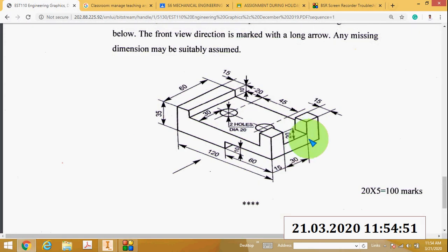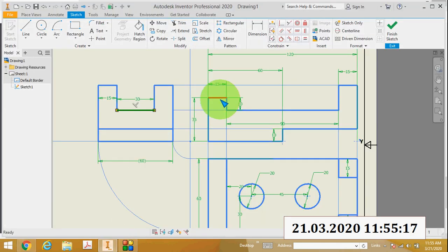And another thing is, when you look from the side view, you will see this line. You will see that portion in between these two structures. You can't see this full edge, but you will see the portion inside this U shape. The other two portions you can't see. So this is that edge. So I will project that edge.